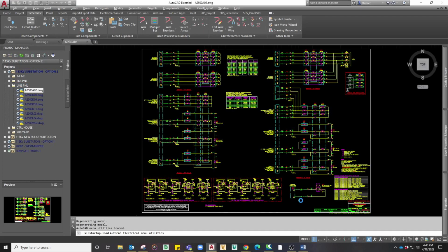The cons are that you'll be creating additional drawings that are going to have to be maintained by your AutoCAD electrical librarian. The upshot is that these drawings, like the distribution panel shown in the example, can be drawn to match a vendor-specific design. When new vendors or configurations are used, it can be pre-built with flexibility for copying and editing to meet your needs of any vendor.